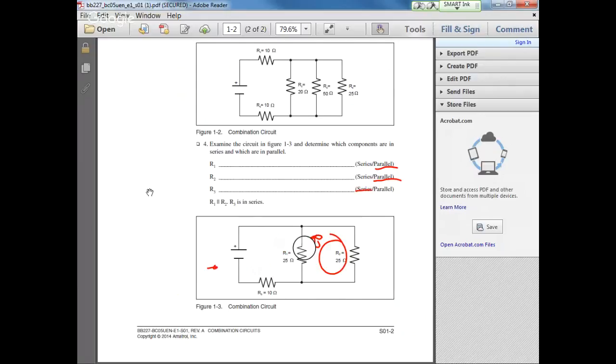They did that because they wanted to show you that it doesn't really matter if it goes in front of the parallel configuration, behind, etc. Now, when we solve these, here's your hint. Kirchhoff's law still applies. So the total voltage drops when they're in series, and the total current that's used when they're in parallel will still add up to be IT and ET, or voltage total. You with me? And current total.